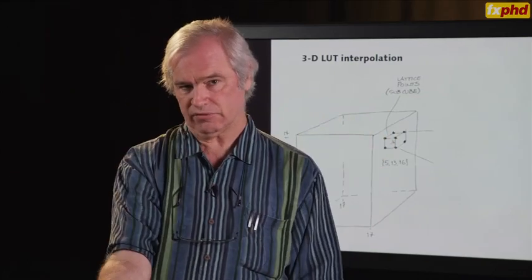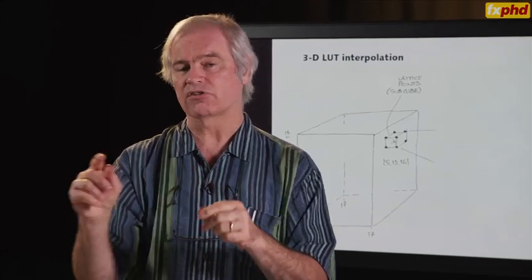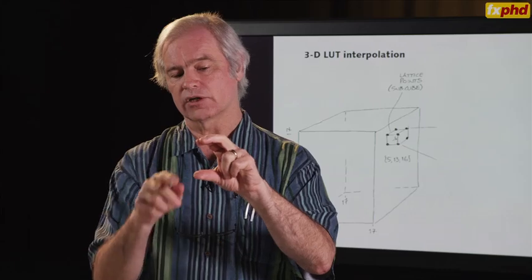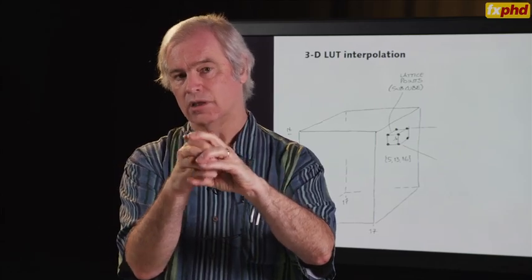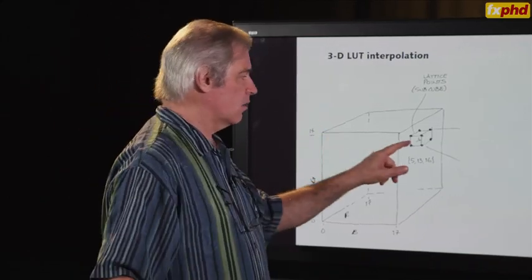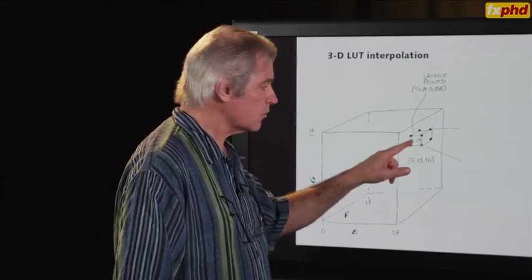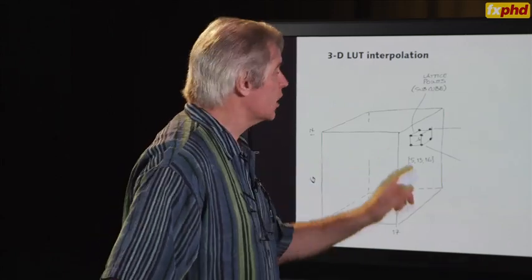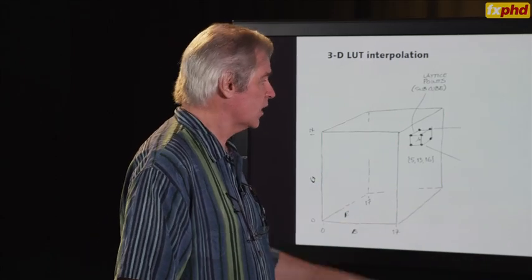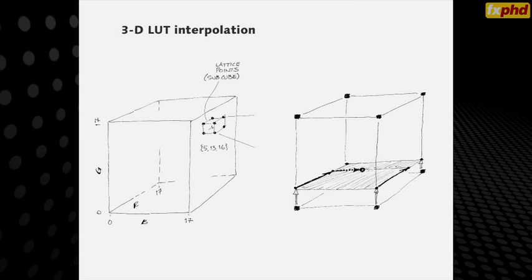And there's 5,000 of those cells. Generally speaking, the color transforms that we need to implement are smooth enough that linearly interpolating across each cell is perfectly smooth in practice, or I should say smooth enough. So we take 4,913 lattice points, or I should say lattice cubes, each with 8 points, 8 vertices, and in that little tiny cube we do exactly the trilinear interpolation that I showed you a moment ago.